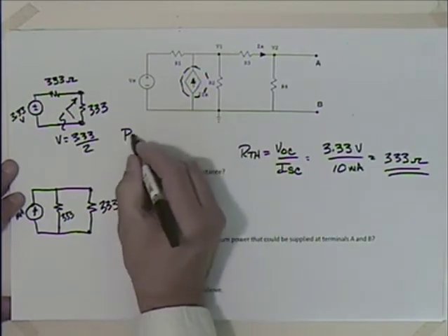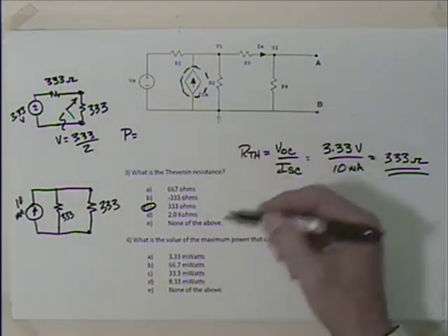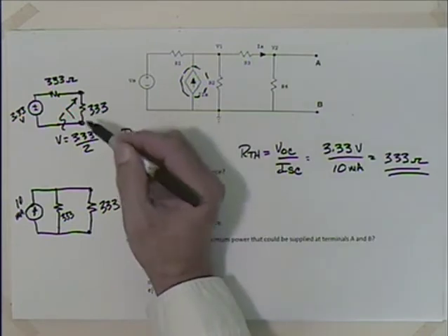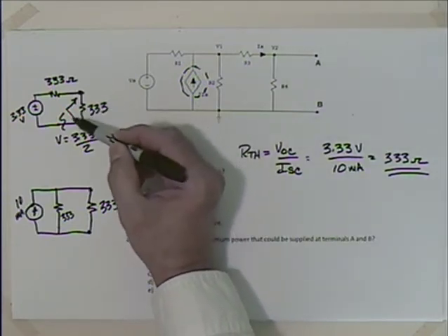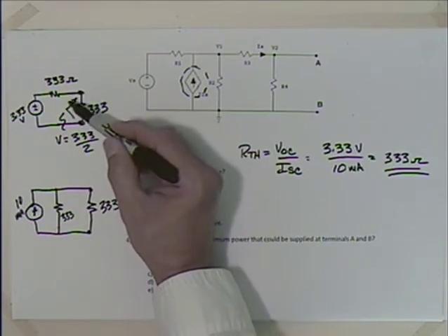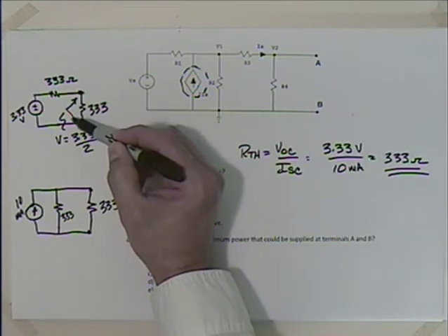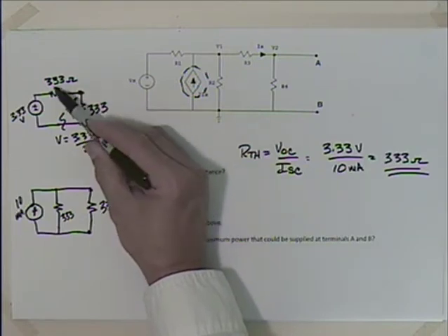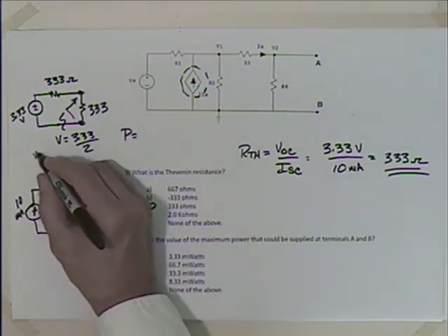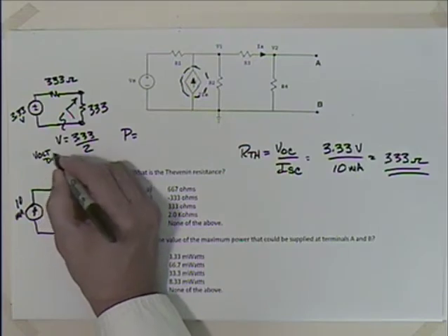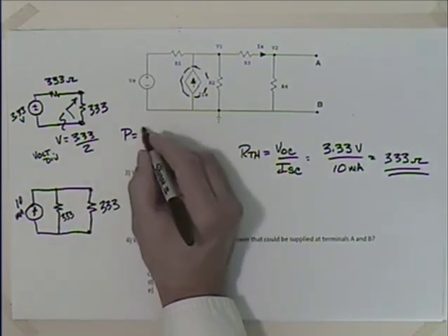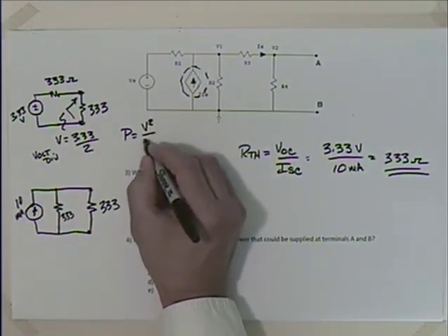And I could say then power is equal to, and remember we had that equation with the 4 in it, and I said I didn't remember it, because I always just drew the model like this, took the voltage as half the value, because when you square half, that's how you get the 4 in the denominator. But anyway, take the value at half the value, because we have an even voltage division. This is voltage division. And then use V squared over R.